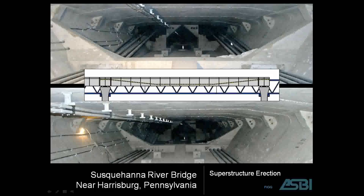We also can see in this picture on the lower photograph an open duct here, which allows for future post-tensioning if necessary. So there's always provisions made for future PT in these bridges. Boxes also facilitate carrying utilities without having them outboard or out where they can be seen, which greatly enhances the aesthetic value of these bridges.